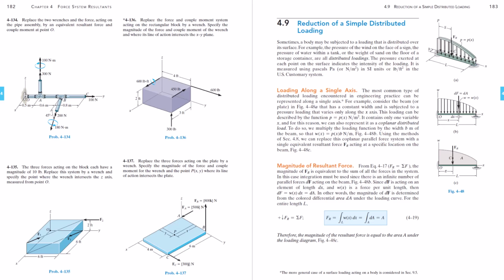If it's not a body force, then the force is going to be a surface force or a contact force. Again, those are the only two types of forces there are. Most of the forces that we observe on Earth are surface forces, right? To transmit these forces, there must be contact. For all surface forces, there's going to be an area of contact over which the force is distributed.